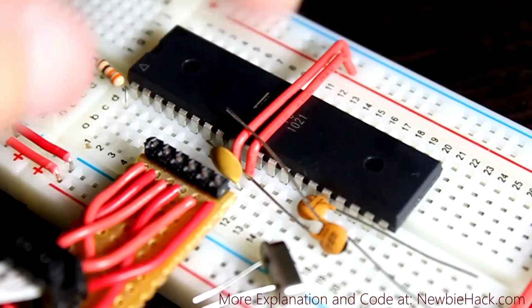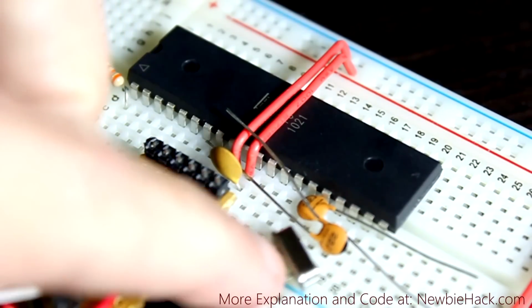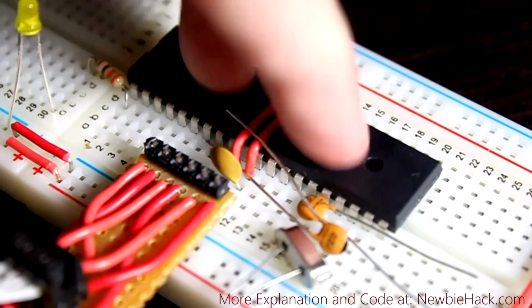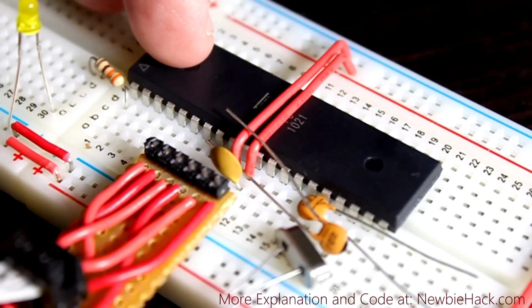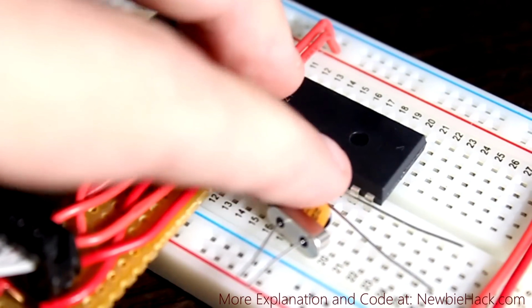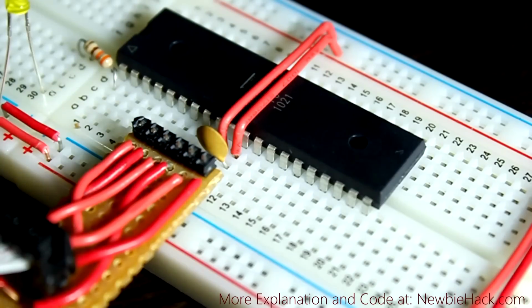So we have to add these components to the microcontroller, and as it sits now, this microcontroller is just a brick. It will not work unless you have the crystal or some oscillating device that will work with the configuration that we've set.